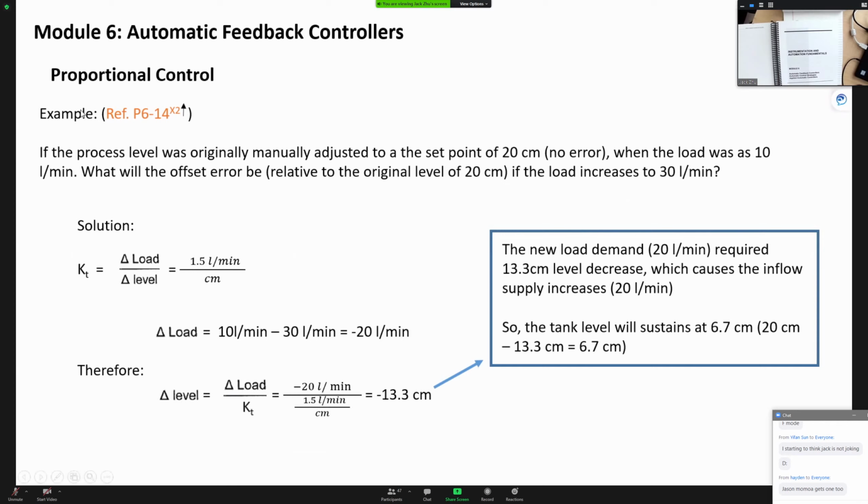If you use a proportional control only, you could see the water level change. If you open the valve to drain more water down there, the VFD will speed up to pump more water from the bottom up, but the water level on the top tank will go lower. Or if you close it, the water level will go higher.